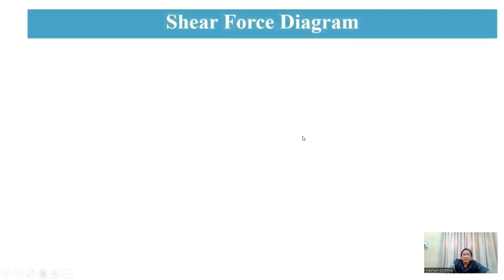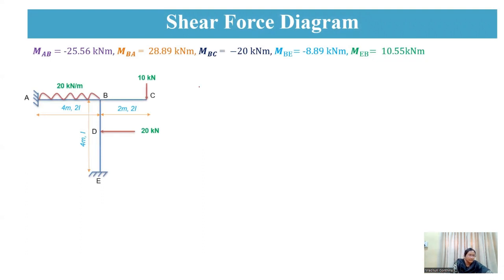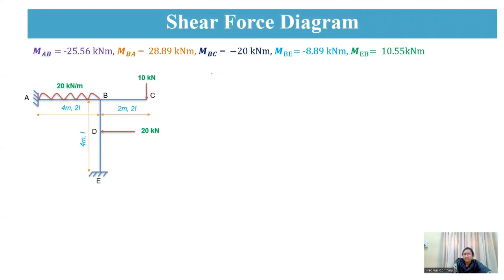Now, coming to the next one, shear force diagram. For the same, for the shear force diagram, we are going to calculate the reactions first. So for that, you are going to draw the free body diagram.